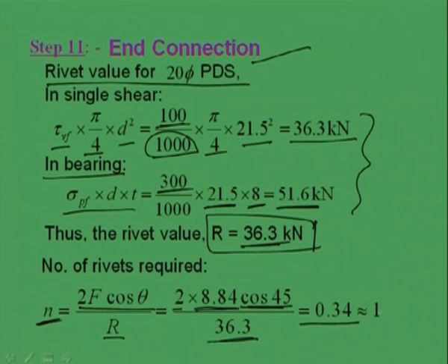So, here we are seeing that we are designing in a conservative way, right, because everywhere we are seeing the allowable stress is much higher than the developed stress in terms of compressive stress, in terms of tensile stress, in terms of the slenderness ratio, in terms of number of rivet required. So, for this case at least we can say that if we use single lacing system, it will be economic.